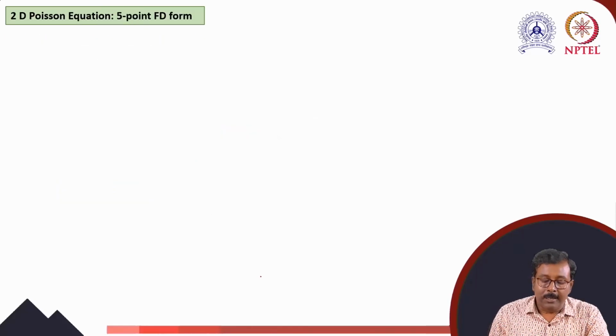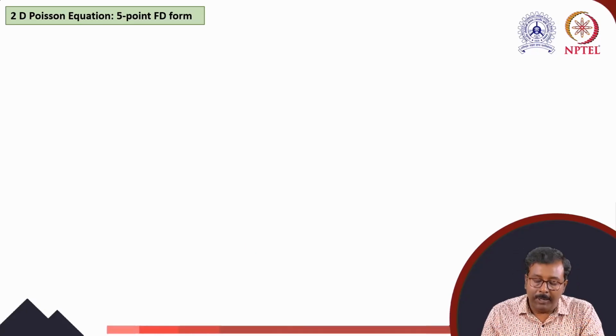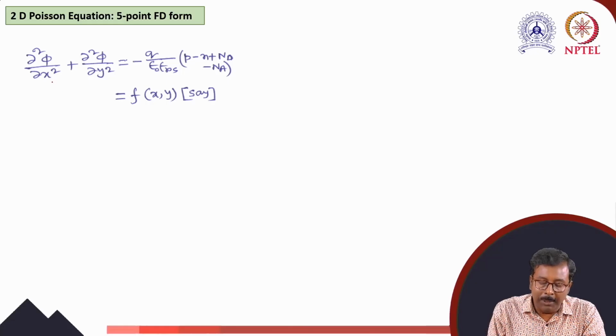Now let us consider the two-dimensional Poisson equation and use the 5-point finite difference form of equations. So the two-dimensional Poisson equation: del square phi by del x square plus del square phi by del y square is equal to minus q by epsilon 0 epsilon r times (p minus n plus Nd minus Na).